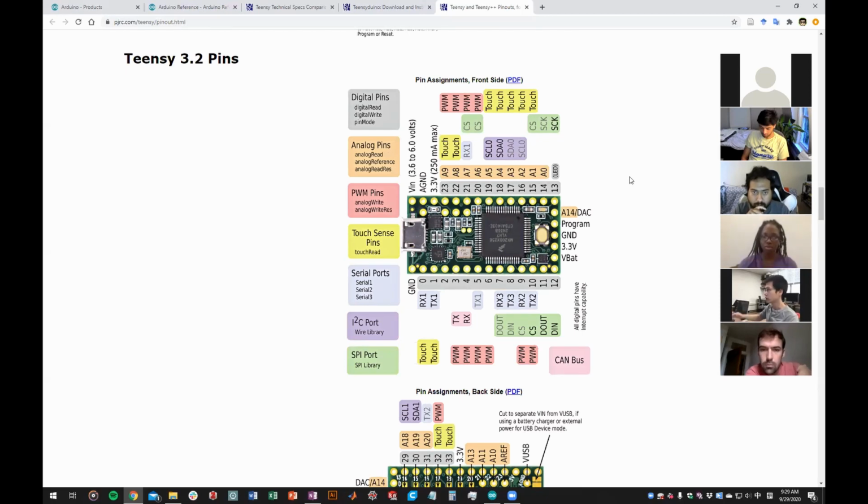For example, you mentioned that you want to use the pulse signal to measure the leaks rather than the electrical leak detection. In those cases, you will be using one of the analog pins. But you can see that some of the pins can be digital and analog at the same time. That has to do with how you assign the pins in the code, and we'll get there.